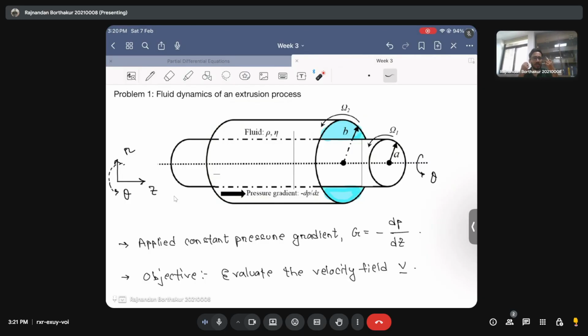So if you do that, and if you give some length to this die, I hope you can realize that when the molten material solidifies, you will get an annulus with a prescribed length, and that's the shape you are trying to manufacture. So the idea is that you put the molten material in between these two dies, and after inserting it, you also need to take out the molten material, right? Only then can you reuse the die for creating the second batch of materials.